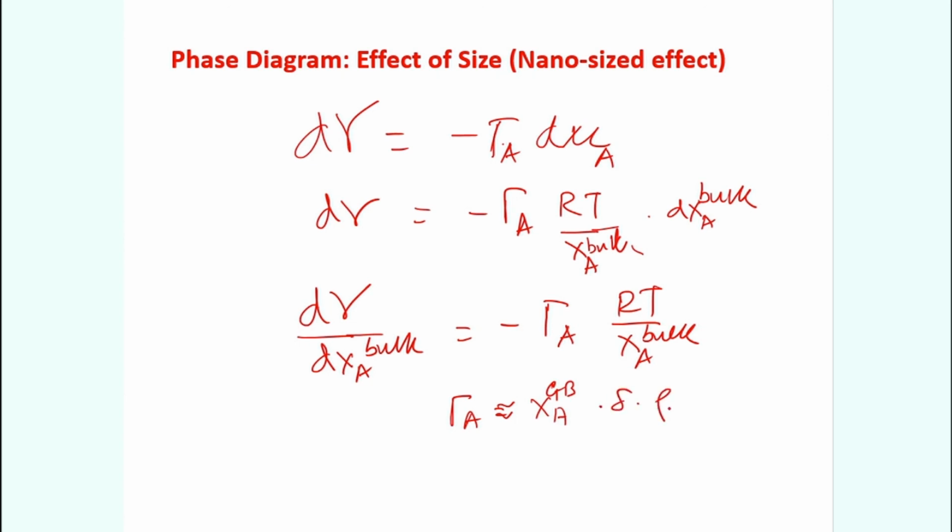Okay, where delta is the thickness and rho is the density of grain boundaries. These are very difficult terms. So, thickness of grain boundaries can be obtained. Density of grain boundaries, well, it will be less than the grains because it has more random atomic structures, but one can actually measure it by looking at the grain boundary structure very easily. You know the grain boundary volume, then you can know the number of atoms present, then mass by volume can be obtained as a density.